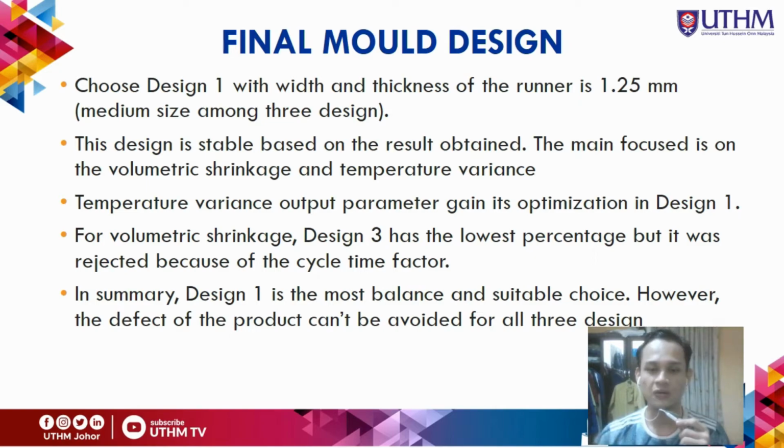However, defects in the product cannot be avoided in all three designs, for a few reasons when designing the product. The defect is a short shot, when the plastic cannot fully fill the cavity 100%. Moreover, the cost calculation shows that the total cost of production for design 1 is the cheapest.